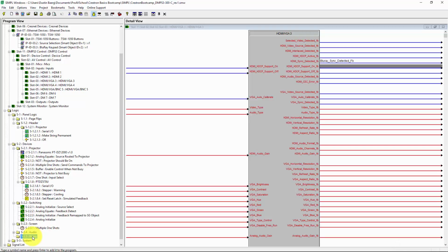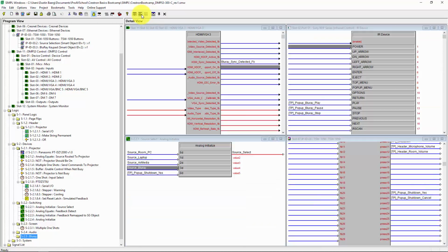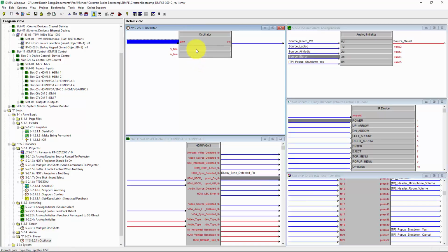And basically I'm going to accomplish this by telling it to turn on and seeing if it has turned on. So first of all, I'm going to have an oscillator because we need something that cycles, that's going to keep checking. And let's oscillate every 8 seconds, say. So high time 0.1 pulse, low time of 8 seconds. So this is every 8 seconds, or every 7.9 seconds probably, you're getting a 0.1 second pulse. And we'll drive this from system on feedback.